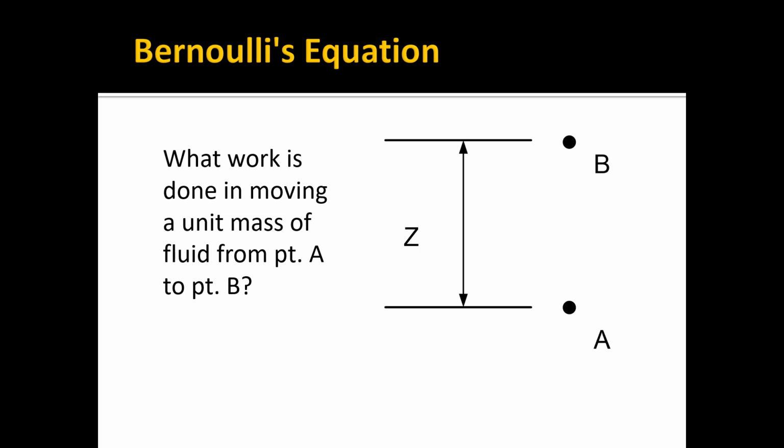And in order to solve this, we are going to look at something called Bernoulli's equation. Again, hopefully this is a review for you. It may have been a while since you've seen Bernoulli's equation. But we are going to rederive it. The way we do that is we look at 2 points, A and B. In this case, we're thinking of points inside saturated soil, and they are separated by a distance z.